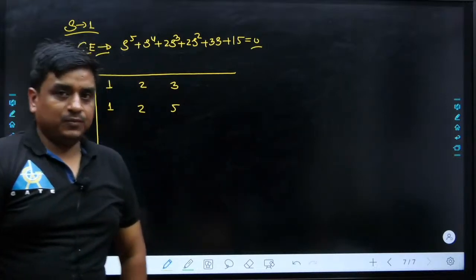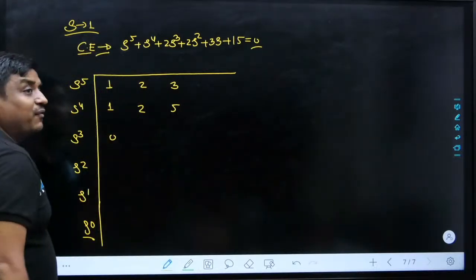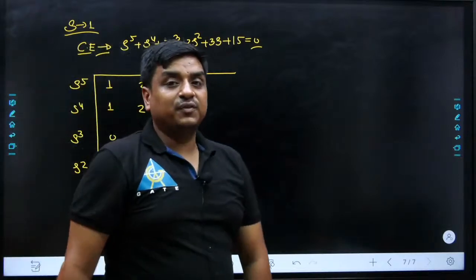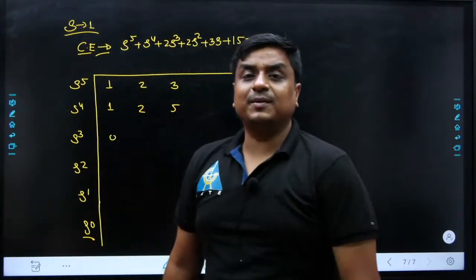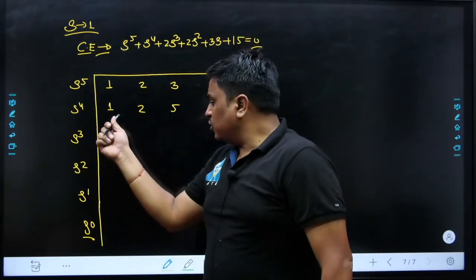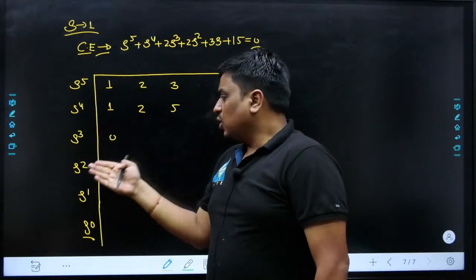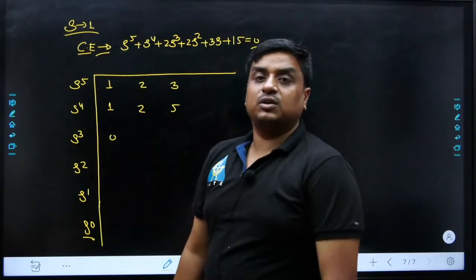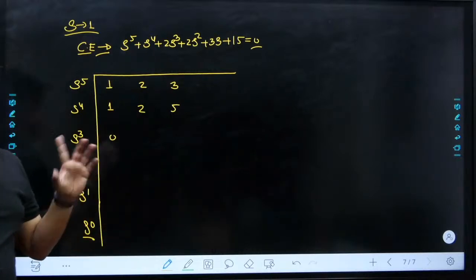Yes, sir. And once we start working this problem out, now the problem has come. The first data has become 0. If the first data has become 0, there are two problems. What? Whether the 0 has to be accepted as positive or negative, that's the first problem. And secondly, I would not be able to calculate the remaining coefficients over the rows s square, s1, s0. Why? Because they require the value of this coefficient.